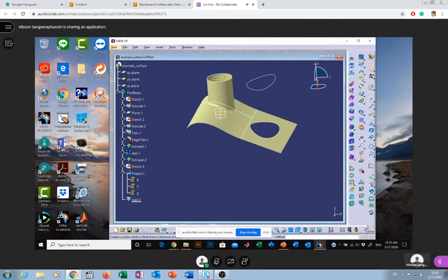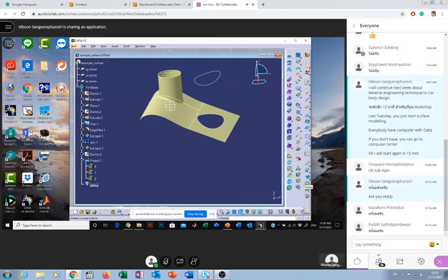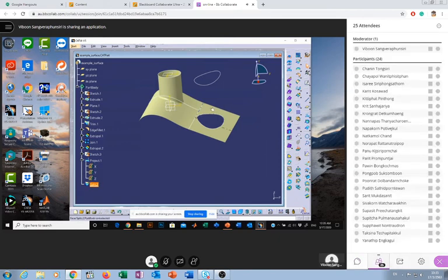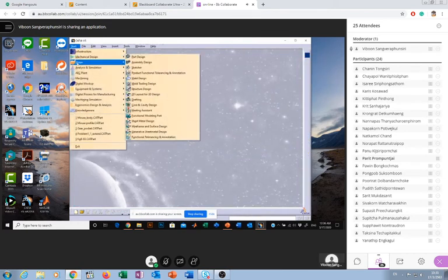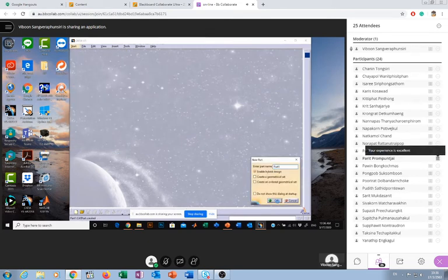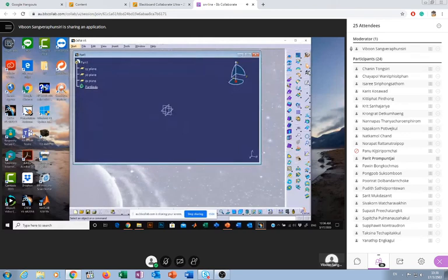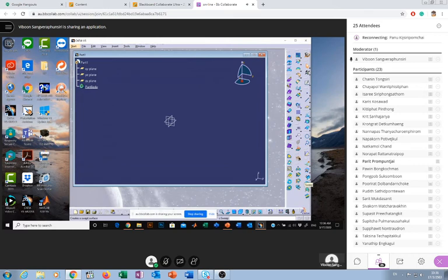Okay, the other one, I showed you a few commands already, as well as multi-section already. I will show you another one, the sweep command. What does it mean by sweep command? Let's see. Shape, geometry, shape design. Okay, sweep in this case is something like a rib command in solid modeling, but sweep is very powerful anyway.